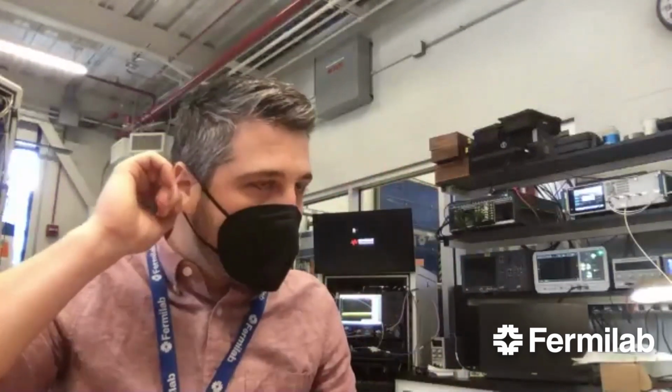The frequency of that cavity, the smaller one, was around 9 gigahertz, and the bandwidth of the filter is probably around 0.1 hertz, while the cavity oscillates at 9 gigahertz. So it's a really nice filter that filters out all the electromagnetic radiation that could, in principle, interact with the qubit and screw up the state of the qubit itself. So the cavity is used to control the environment around the qubit, and also for the readout, as Silvia was explaining.